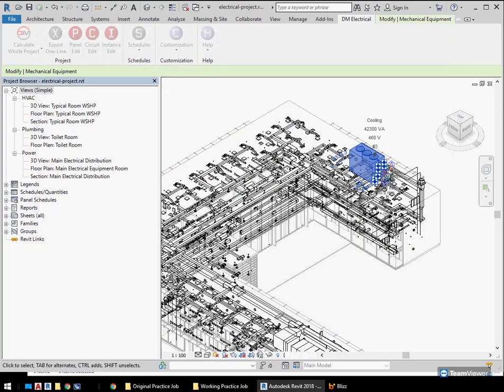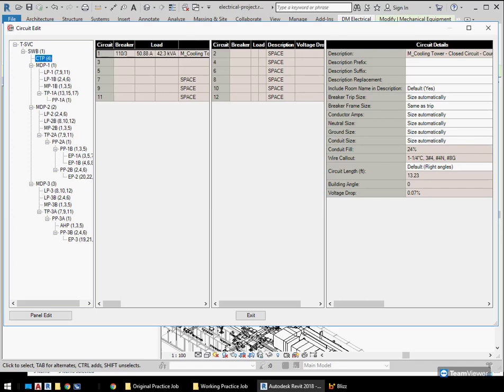So we'll leave everything being pulled from the family, and we'll go look at our circuit definition. And here, you see that the breaker, we set our FLA at 45, which is going to make the math more complicated than I meant it to be. So we get 250% of that, so that's why we're getting the 110 amp breaker. But then the wire size is being based upon the loads. So it's going to be, I happen to notice, a 70 amp load on there, so it's giving us a 70 amp wire.